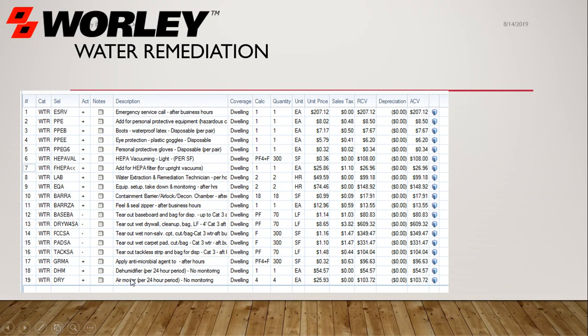Again, I've got everything out of the room that was wet or contaminated, so there's really not a lot to dry, but there's still heavy moisture vapor in the room, so I want to make sure that the porous floor is dry, any exposed wall frame would be dry, and I only give them 1 day for that.